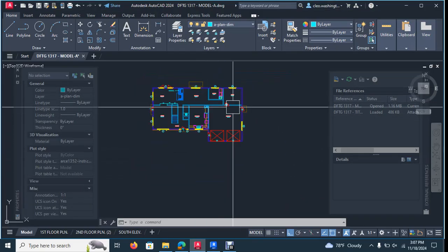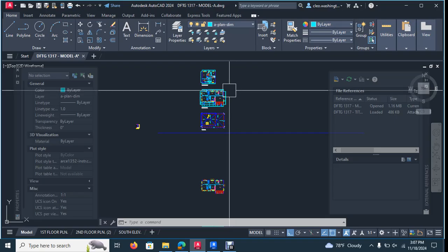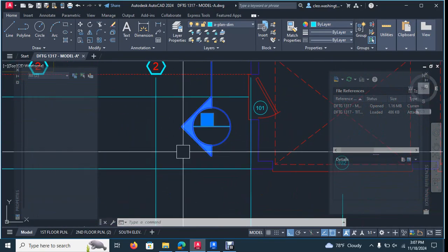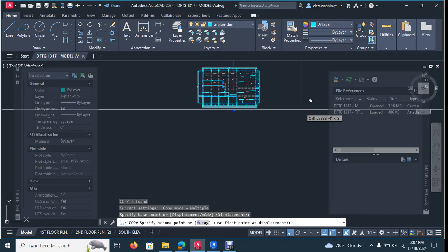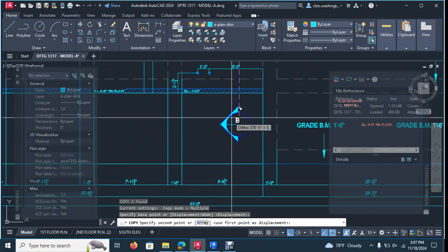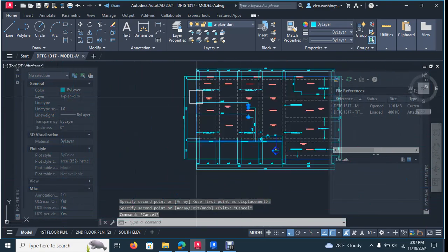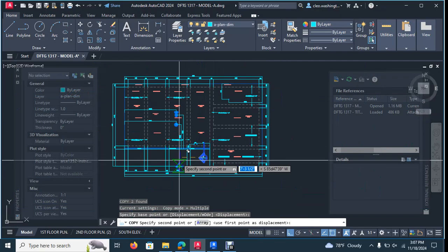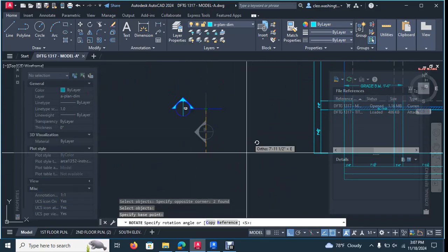Oh, one last thing. Let's do this, because we need to show where those details are going to be cut. So we'll take this guy here and copy it down, because we need to show this on the foundation plan. Okay, so we're going to have one cut that's cutting through the brick wall, right? And then we'll have another cut. And we'll go back and label these later, but right now I want to show that at least we are acknowledging where the section cuts are.